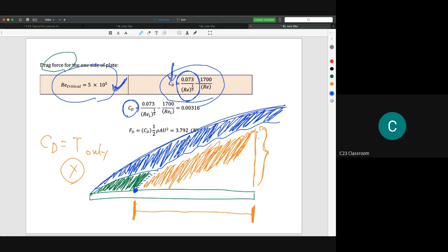The idea is we calculate the drag force with 100% turbulent first, and then we deduct a certain parameter to reduce the unnecessary part here, because we only take care of the laminar part here. But this number comes from curve fitting. People doing the experiment plot a few things and then give some prediction of the value.